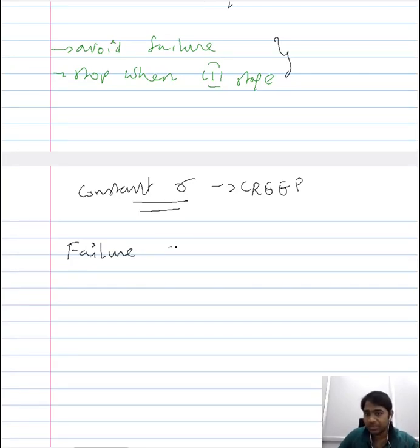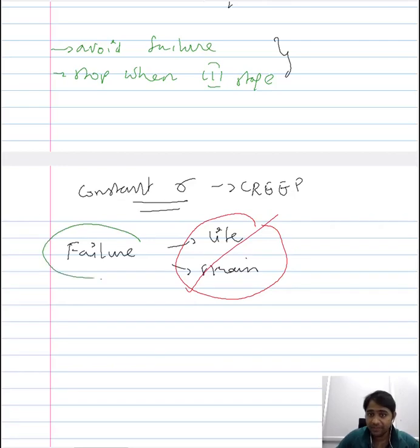So instead of focusing on the life and strain, when your focus shifts to the failure of the material, then you have to make some changes to the creep setup or the considerations that you have made for the creep testing, in order to efficiently understand the failure of the material at high temperature. So one such important consideration is associated again with the stress. We saw that when you consider a constant stress condition, then for any deformation that precedes the failure, say necking that sets in before the failure, the stress accordingly is reduced, and therefore the duration of the test is unnecessarily prolonged.